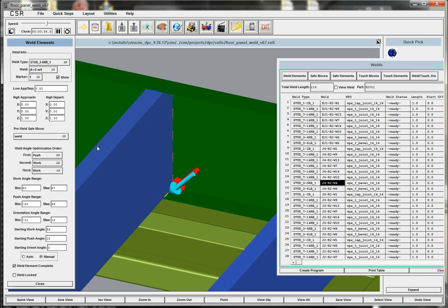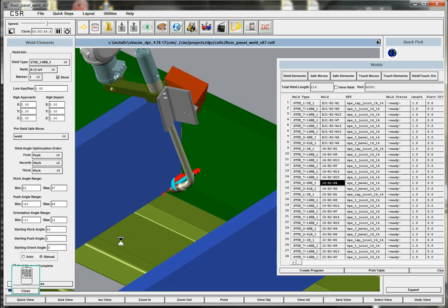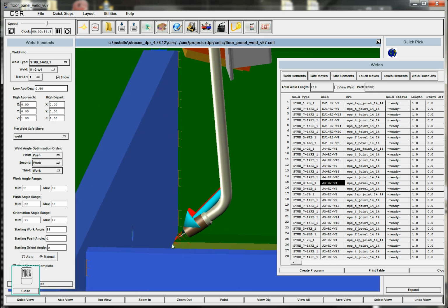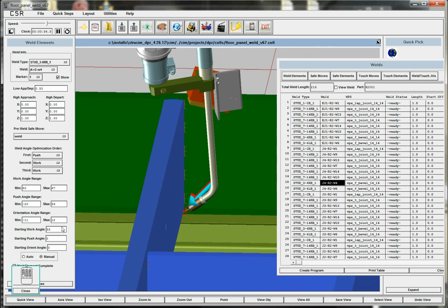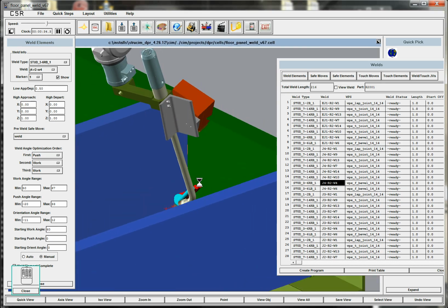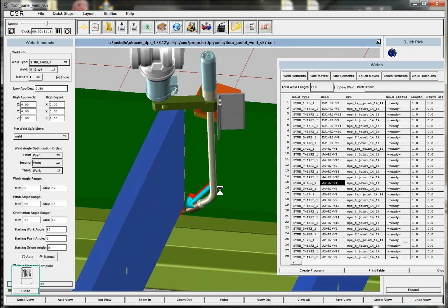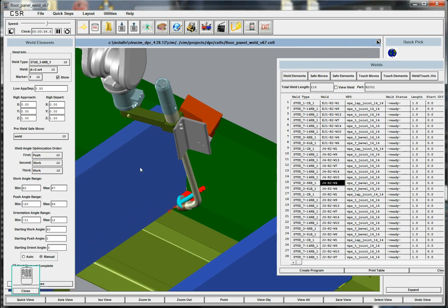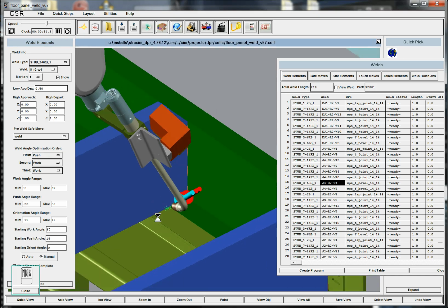And then for the weld, we can put in manual components of what we want. For example, this is a weld with a 60-degree angle torch, so this is at 55, it tilts a little bit in. If we change this to 60, you can see that the torch is straight up and down this way. But we can see that the laser is going to intersect it here. That's why we're adding a little bit of a push to move that back a little bit.